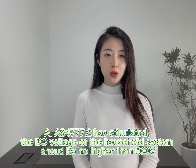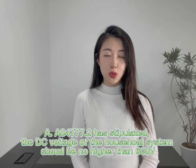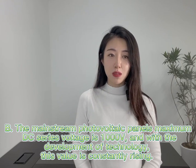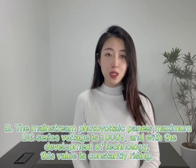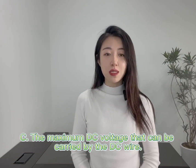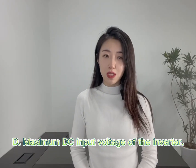A. AS/NZS 4777.2 has stipulated the DC voltage of a household system should be no higher than 600 volts. B. The mainstream photovoltaic panel's maximum DC series voltage is 1000 volts, and with the development of technology, this value is constantly rising. C. The maximum DC voltage that can be carried by the DC wire. D. Maximum DC input voltage of the inverter. Only when the DC input voltage meets the above 4 requirements can it be included in the calculation of the number of photovoltaic panels installed on your house.